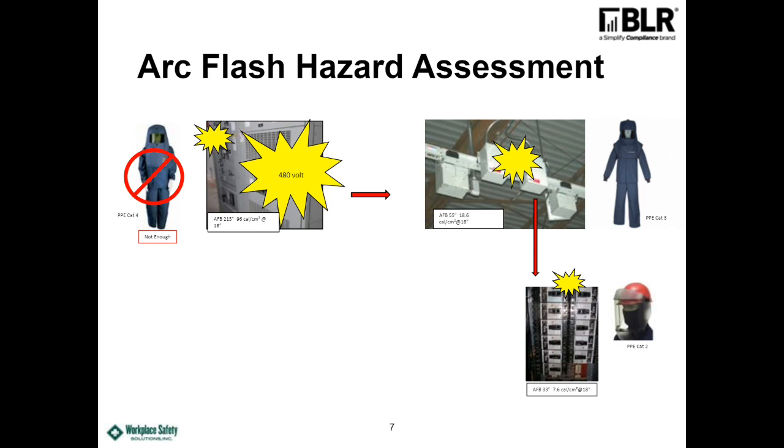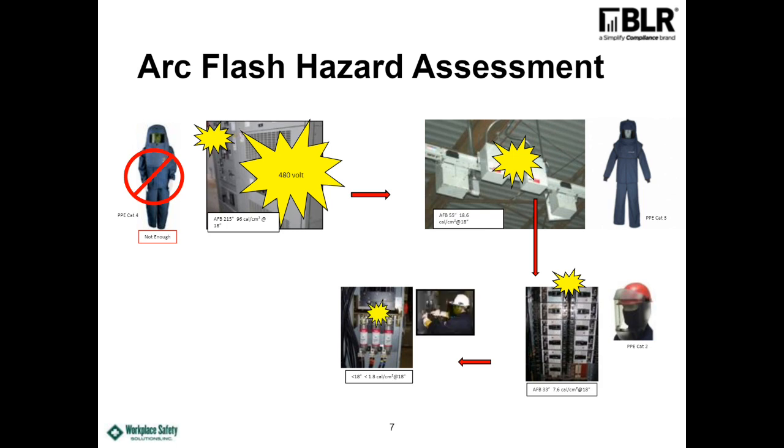And then from there, you're going to go downstream, probably from one of the other breakers, and you're going to feed this disconnect switch. You're down to 1.8 calories. So you're still over 1.2, which means you're still going to wear a shield for this protection.